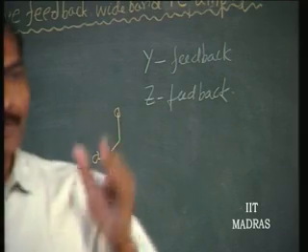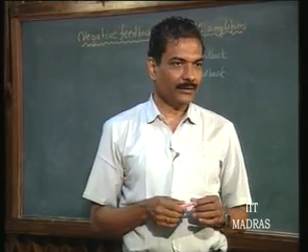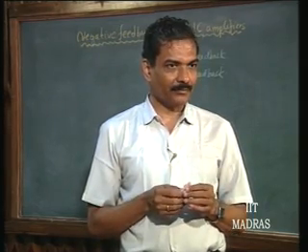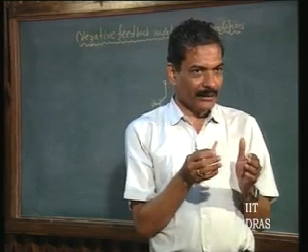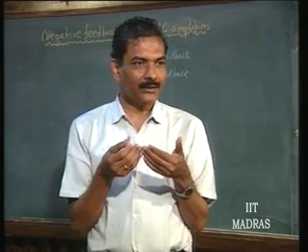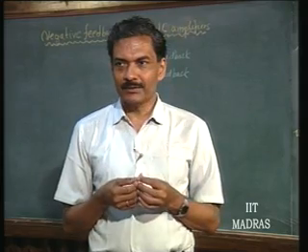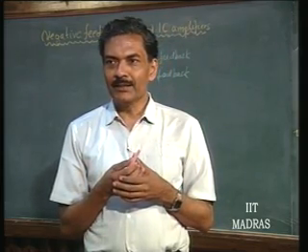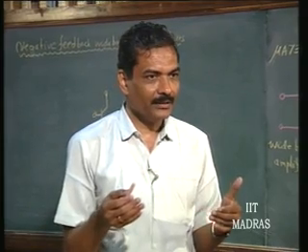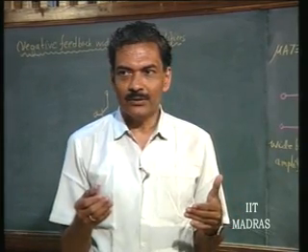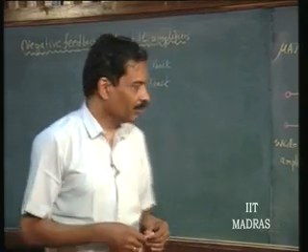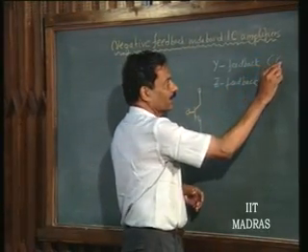What is the purpose of this type of feedback? Let us say Y feedback. Input admittance and output admittance, what happened to them? Right? Input admittance is increased, right? That means input admittance is made to go towards as high a value as possible. Right? Output admittance is going to be increased, right? That means it is leading you towards idealization of what kind of amplifier? Current controlled voltage source. So, this is going to lead you towards a current controlled voltage source.